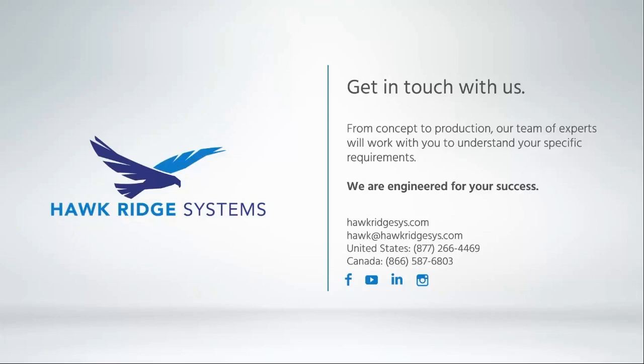And in regard to Nina's question about her properties not migrating into the title block on her drawing, you'll definitely want to check your template for your drawings to make sure you have the correct mappings, and also that you have the correct variable mappings for PDM. It's just a few things you'll probably need to look at there.